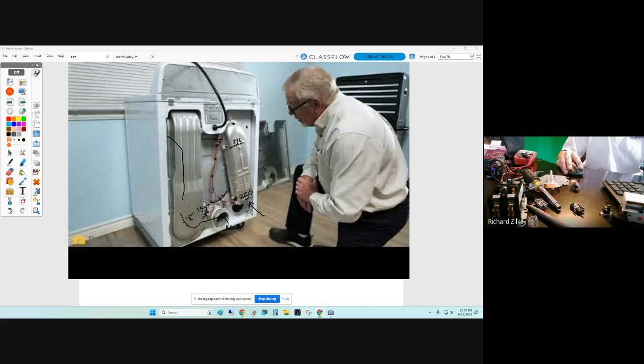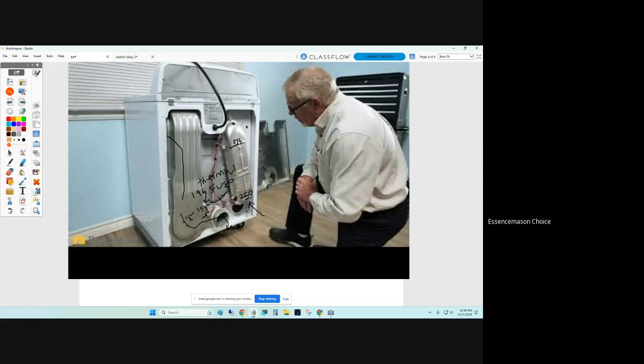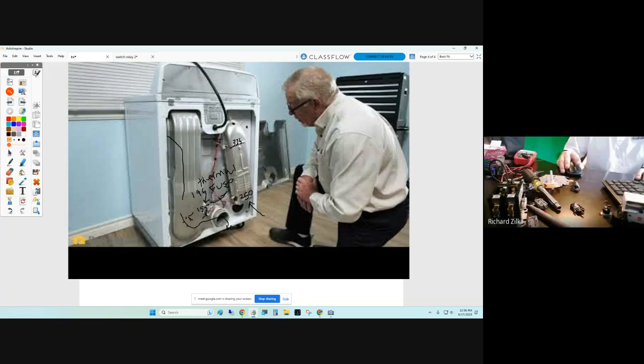Now, one thing we didn't talk about is there's another piece right here behind that thermostat called the thermal fuse. Does anybody know the temperature of that? That's 196. Just above 155, but not so close that it'll go bad by mistake. But 155 degrees here will turn the element off. But if this fails, now the temperature goes higher, less than our high limit, 196, that thermal fuse will blow.